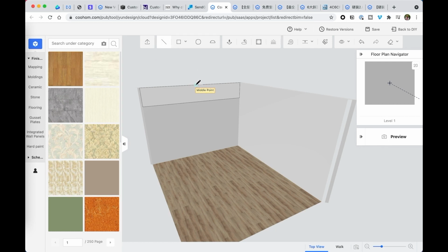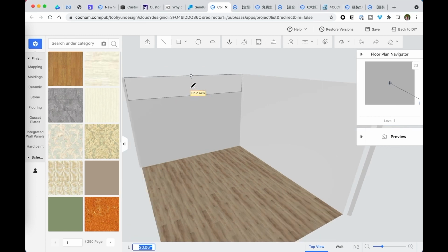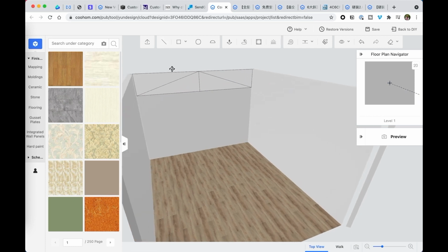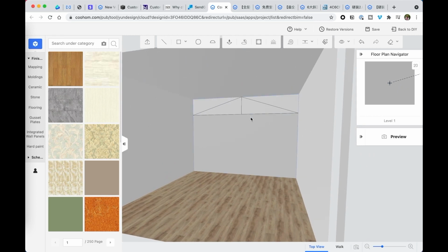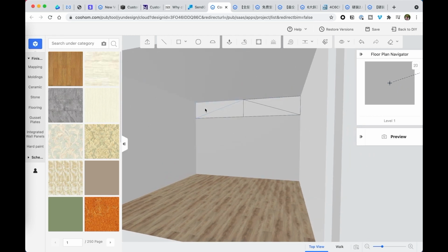The basic principle to draw a tapered ceiling is to draw the shape. Using the line tool, you can conveniently divide two spaces. By dividing two spaces, you also see there is a color. If you zoom in a little bit, when you're extending the line, that means your line is perfectly vertical on the z-axis. By dividing this line and connecting it, this is how we get an angled edge here.